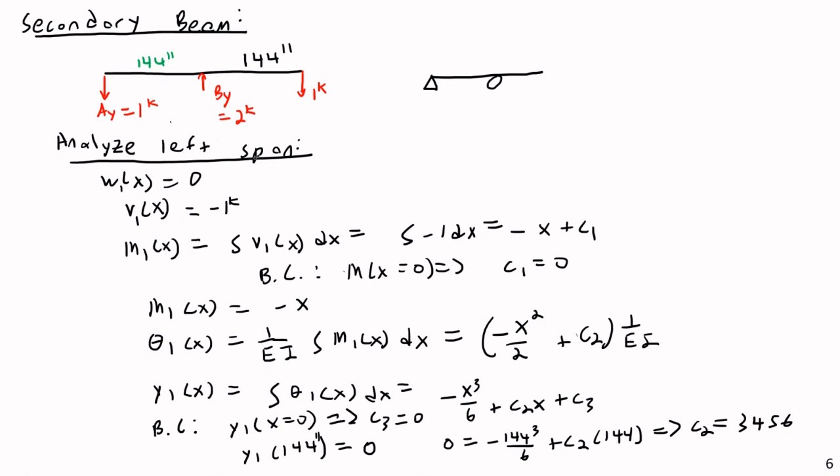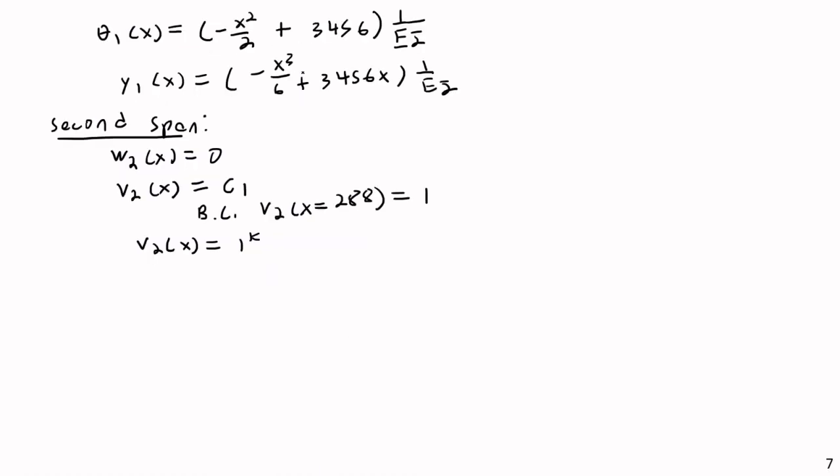While we were at negative 1 kips prior, because initially our shear and bending moment diagram dropped down 1 here. Basically, the shear diagram for this starts at negative 1, remains constant, jumps up to positive 2, then remains constant, then drops back down to 0. Okay, so we have our shear, no great problems there.